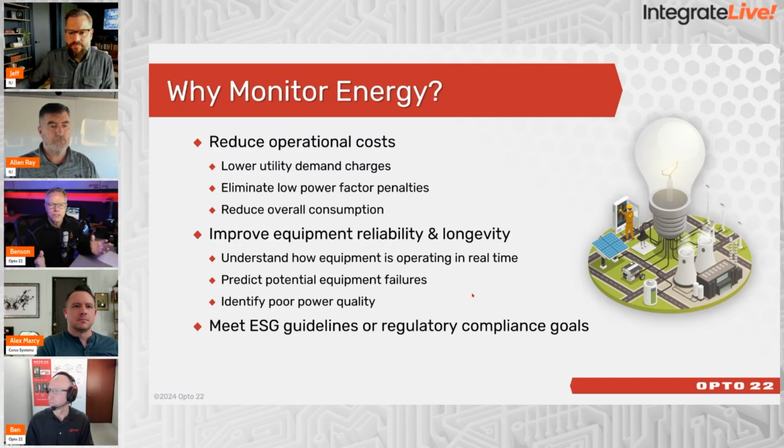And demand charges are different than how much energy you use over time, which is measured in kWh. Demand charge is measured in kW. kW is the amount of energy you're using at any one given time. And a big portion of our bill, anywhere from 30 to 50% of your bill, is on demand, how much energy you're using at some point in time during that billing period. And you can't manage what you can't measure.